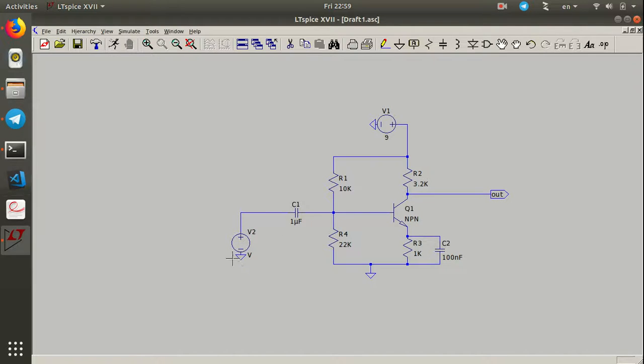Because when you hit the strings of your guitar, it generates a very small voltage, and the voltage is actually at the frequency of the note you are playing. If you play a note A at the frequency of 220 hertz, here we will have a very small voltage, and this circuit just distorts that signal and feeds it to an amplifier if you set your distortion pedal in the preamp setup.